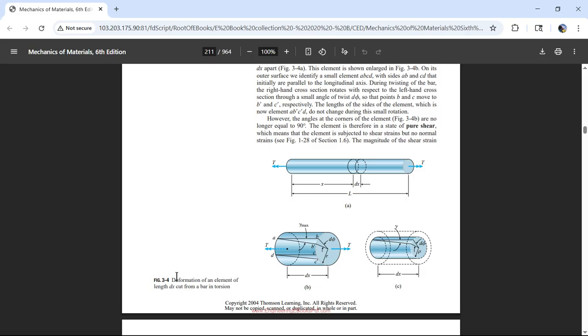So as you would shear this up, those two down, this distance increases and you get a break. And the break happens at a 45, and that's going to propagate at a 45 and spiral. You're going to get a spiral fracture. But that is just for things that can't take tension.